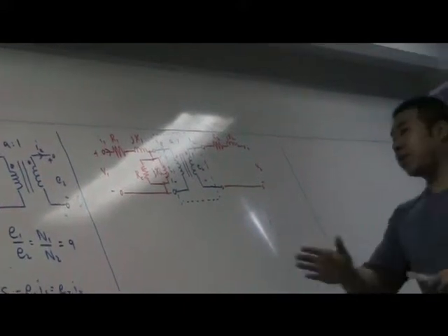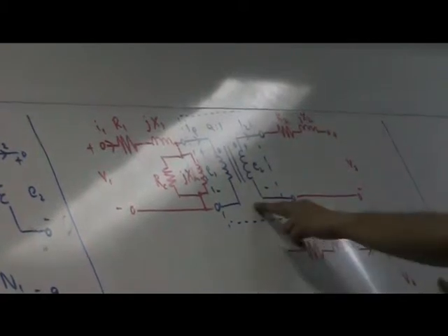So we take it 4.2. You're supposed to refer everything to the low voltage side. So for this question, I will bring everything from the primary side to the secondary side. When I remove the ideal transformer, I bring everything from here to here. Everything on the right hand side, the secondary side, stays the same. Nothing changes.